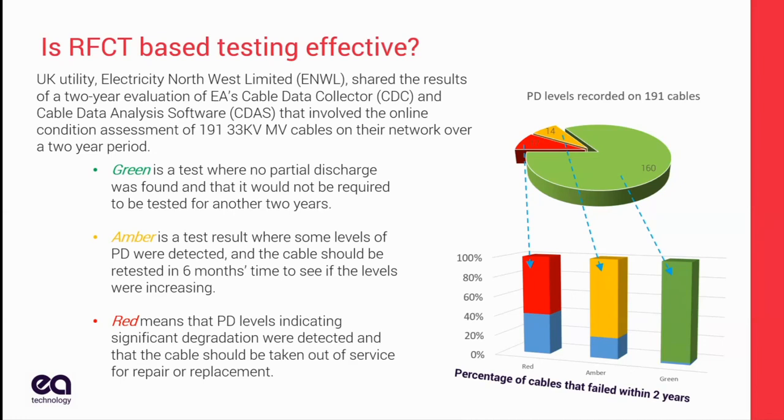So as you stand there and you look at 191 cables, I don't know what to do. I don't know which ones are going to fail. I can't take an outage on any of them. I'll do nothing. That's what happens. Here, I do the test. The test is quick, easy. The repairs may not be, but it's always preferable to do a repair than to wait until it fails and then get called out in the middle of the night, because like babies, cables fail. Cable failures come in the middle of the night.